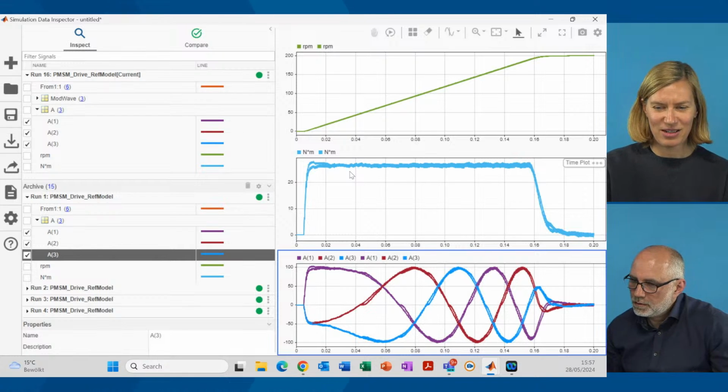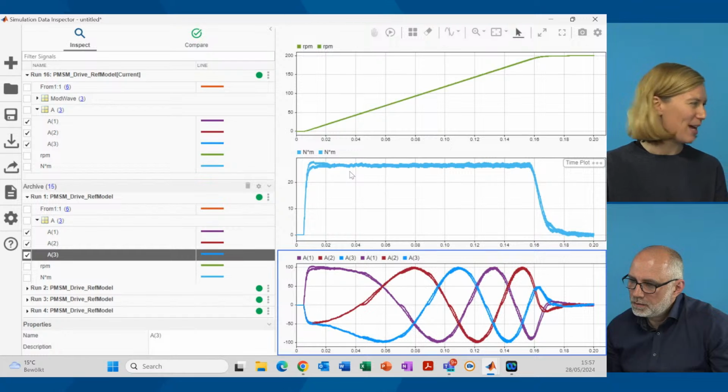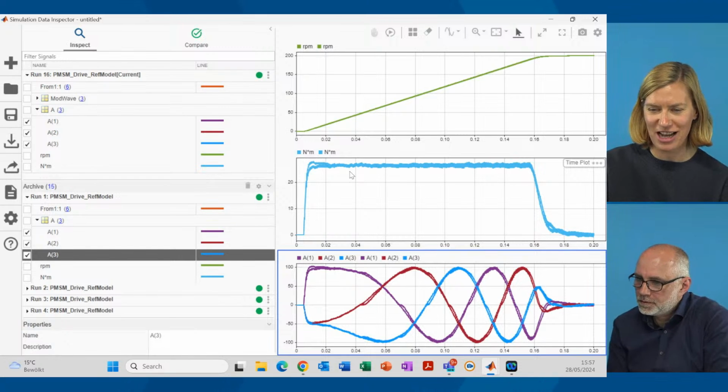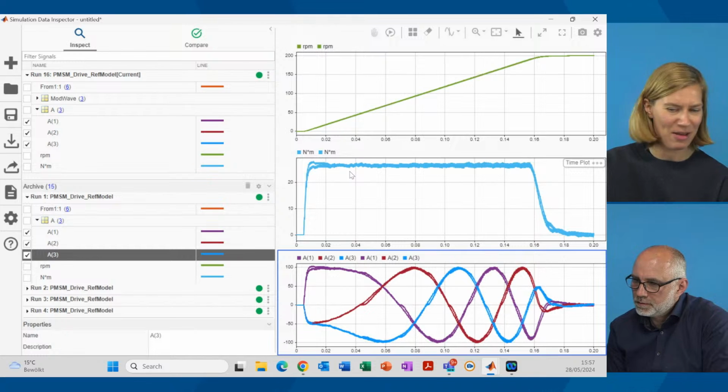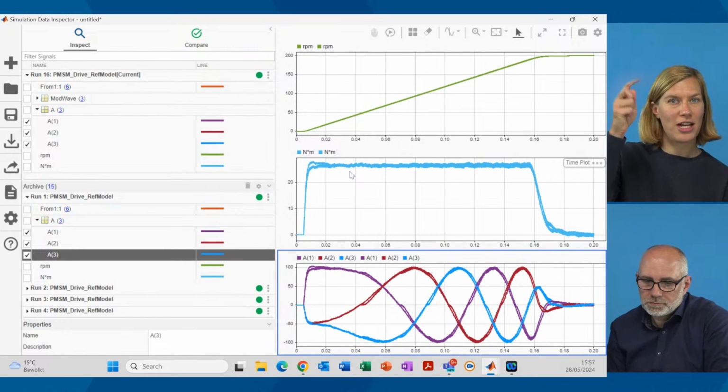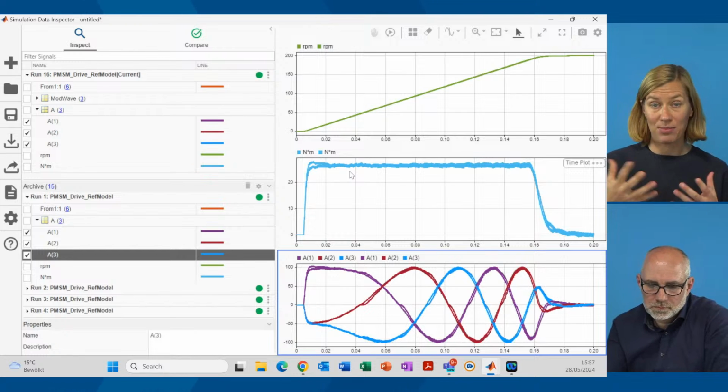Brookflix is asking, apparently cannot see the same type of solver settings we are seeing, or the types of solvers. I might not be understanding the question 100% correctly, but if you have Simulink, you should see all the solvers we had available. So maybe make sure to change between variable and fixed step. Depending on whether you choose variable or fixed step, there are different types of solvers available.